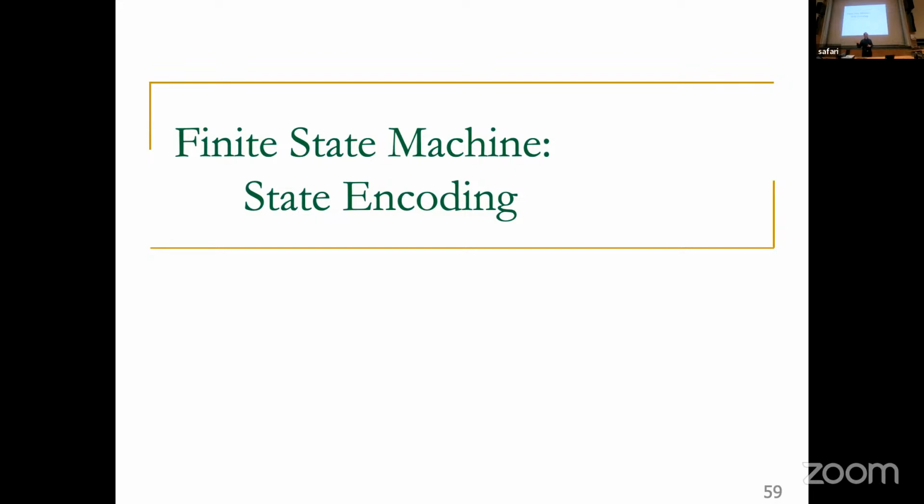And we will see that when we talk about pipelining, for example, later on in the principles of design of microarchitecture. So I'm kind of getting ahead of myself, but all of this will be building up to a microarchitecture that processes instructions. That instruction processing can be done in one single clock cycle, as we will see. And we will see that that's a very long clock cycle. So we're going to chop it into pieces such that your clock cycle can be shorter. But now you need to design a finite state machine that processes instructions in an appropriate manner in multiple clock cycles. So whatever we're going to see in a few lectures is going to build directly on top of what we're seeing right now.